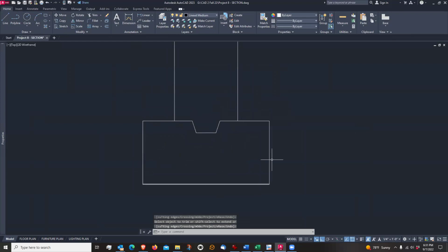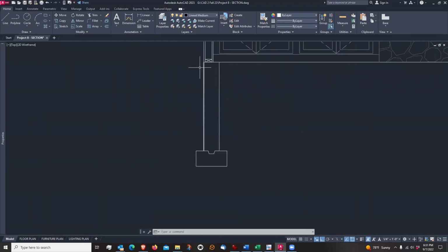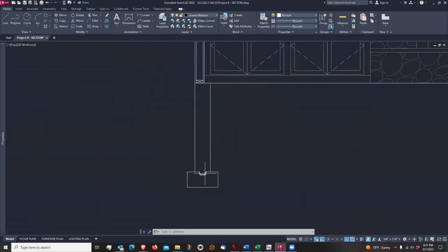So after this footing is set, they rip out that wood stud key, and that leaves this keyway, and then they form the walls, and then they pour this foundation wall.